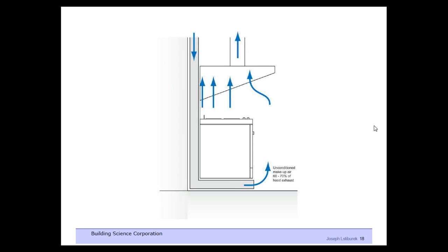That brings us to one of my all-time favorite controversial subjects. You can't put a kitchen hood that is extracting at 100 to 200 CFM into one of these apartments without providing interlocked makeup air, which is why most apartment units don't have kitchen exhaust hoods.